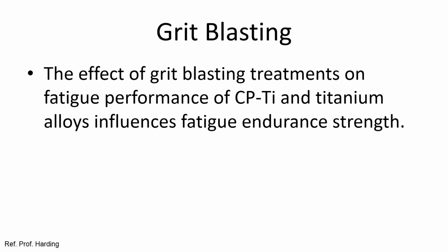Grit blasting is used primarily on our implants to produce a roughened surface. The roughened surface is very beneficial in the formation of early osseointegration, and it increases the surface area of our implants. But grit blasting comes at a cost.